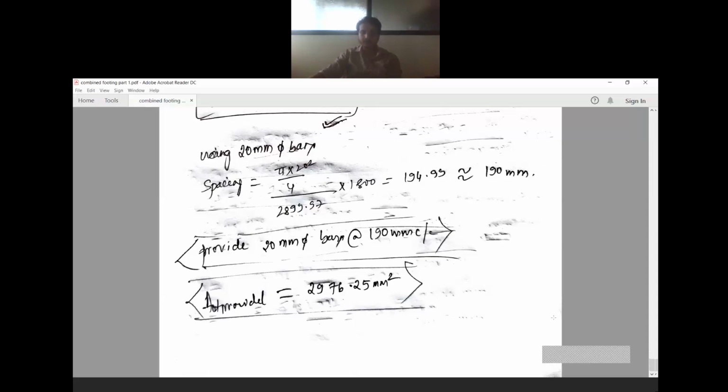One-way shear is the shear check we used to perform while doing the beam problems. Now, we already have the two-way shear, the punching shear value. According to the punching shear, we have already provided some reinforcements. For the same, for one-way shear, we have to provide the reinforcement. If the parameters are within the safe permissible limits, then we shall provide just nominal